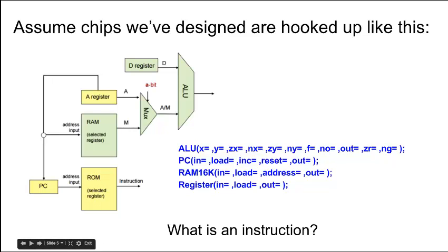So what do these instructions do? Well, they turn on these registers. They enable them. They cause them to load. They cause them to add, increment. They select one of these lines, A or M, going through the mux to feed it in here to the arithmetic logic unit. So they're basically playing with the control lines. Like the reset right here, they're going to control. Increment, they're going to control. Load, they're going to.